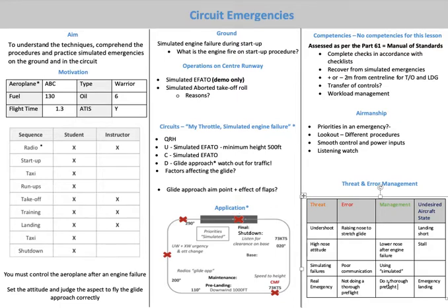Simulate an aborted takeoff practice in the takeoff roll, which we'll both have a look at. All you do is close the throttle and apply braking as required to stop in a straight line. For directional control, use your rudder. The reasons could be a bird strike, poor weather such as thunderstorms in front of you, static RPM not achieved, T's and P's not green, or airspeed not alive.